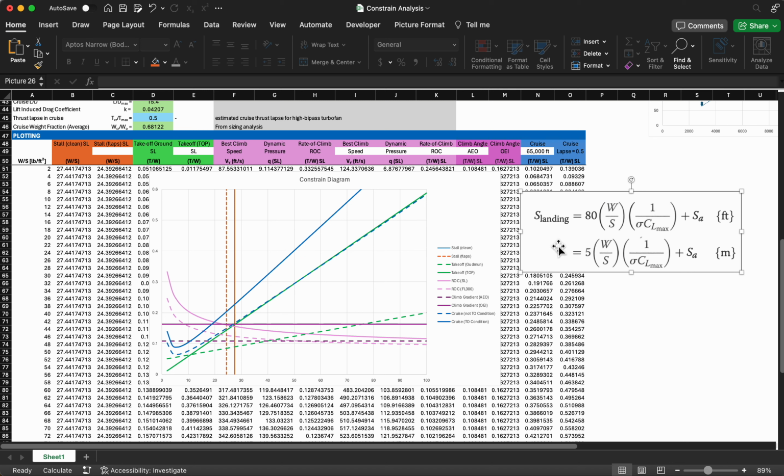And then one more thing, if we have an aircraft that's going to be certified under Part 25, then we should take that total landing distance requirement and divide it by 1.67. So the reverse of what is in the text. This equation is if you wanted to estimate the landing distance. The textbook suggests add 67%, or multiply by 1.67, to the total landing distance you calculate to give the required safety margin.